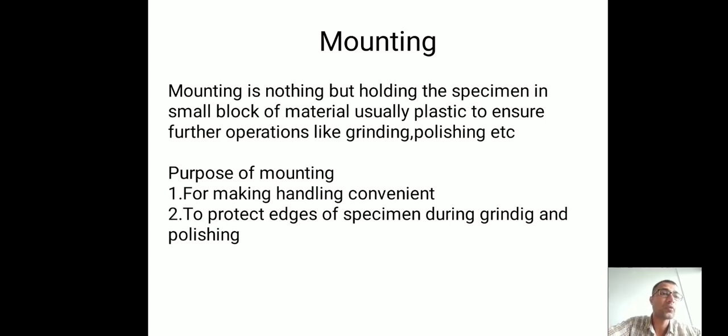Those also we can perform on that section, if we mount it, if we hold it on the plastic material, then it is possible. So to mount means to hold our section on another material like plastic, so that we can perform other operations like grinding, polishing and many more on the particular specimen.